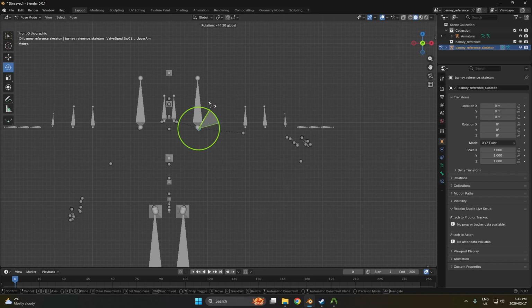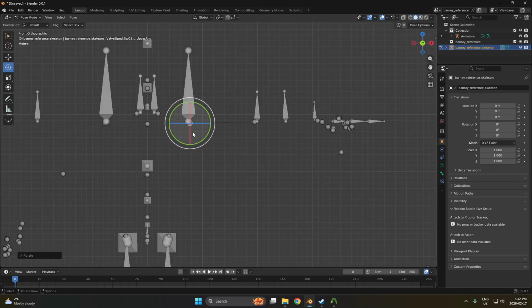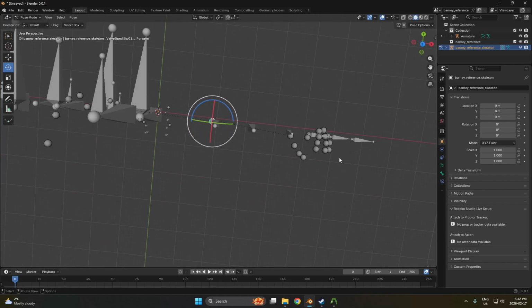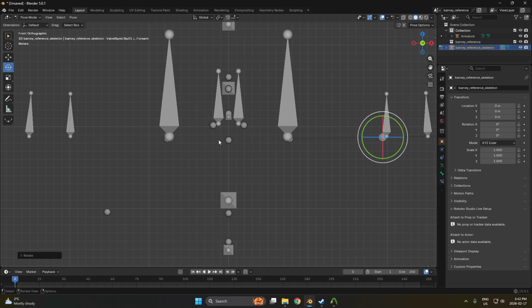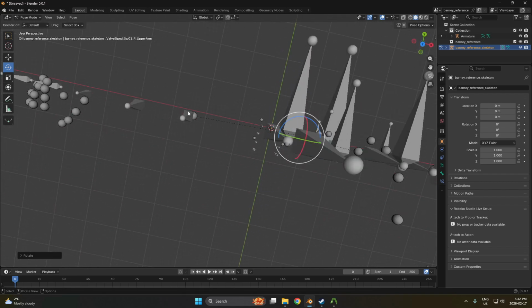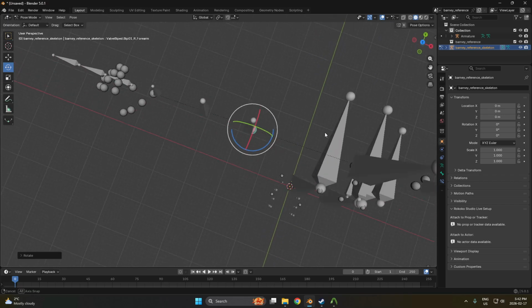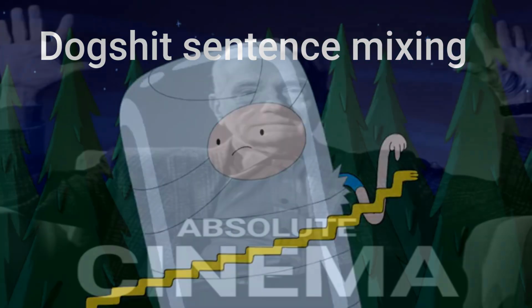Alright, and next you're going to want to pose the source's skeleton to match the same bone positions as the Endorphin skeleton bones. The closer your source's skeleton bones match the same positions as the Endorphin skeleton, the better the animation result will be in Endorphin. Very quick warning, do not, and I repeat, do not move the Endorphin character's bones to match your source's bone positions. This will cause you more pain than needed, trust me. You stay away from that!